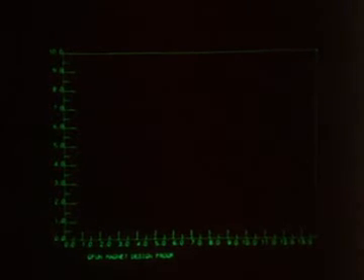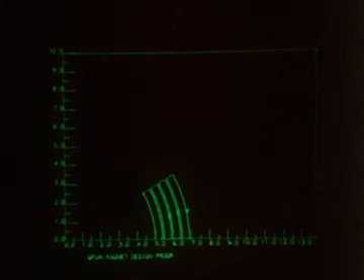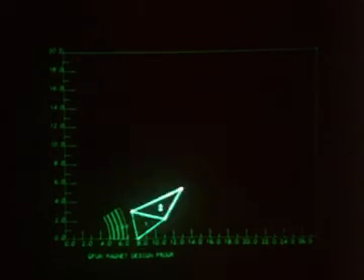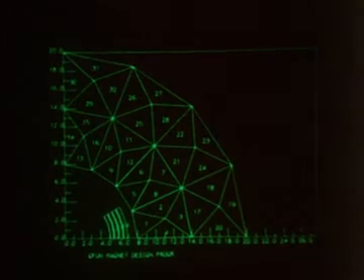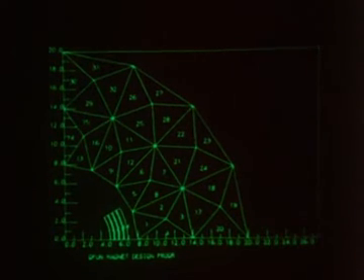The data for the 4 sectors is typed in with each arc set to 30 degrees. Only one quadrant of the magnet is displayed because of the dipole symmetry. To contain and to enhance the magnetic field, a cylindrical iron yoke is required. The designer specifies the yoke geometry and chooses to represent the cylinder by 32 triangular elements. The program automatically divides the cylindrical space into the required number of triangles.